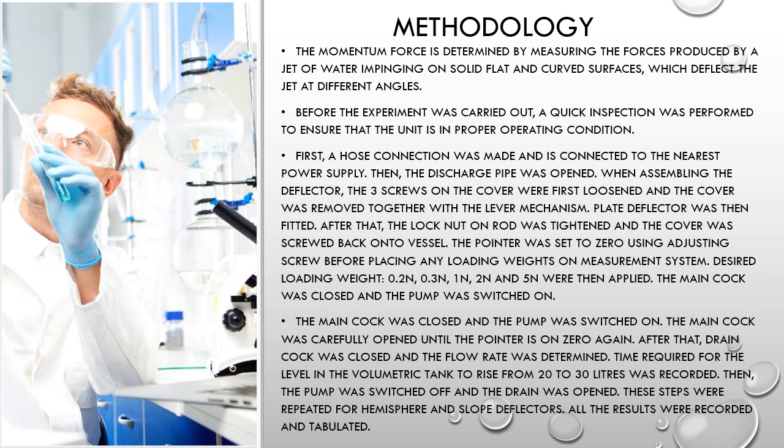Now, for the methodology, the momentum force is determined by measuring the forces produced by a jet of water impinging on solid, flat, and curved surfaces, which deflect the jet at different angles. Before the experiment was carried out, a quick inspection was performed to ensure that the unit is in proper operation condition. First, a hose connection was made and is connected to the nearest power supply. Then the discharge pipe was opened.